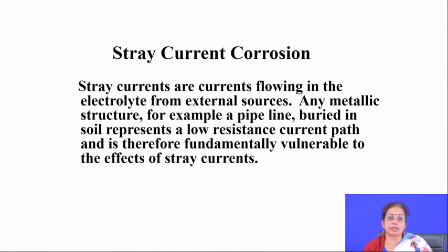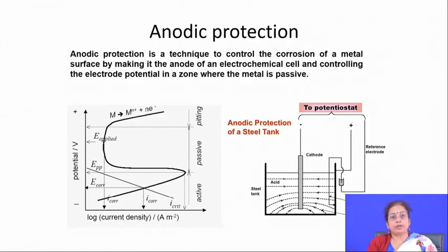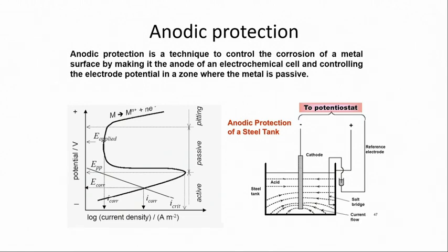Whenever you use cathodic protection, particularly below the earth, especially when you connect it with DC sources, you will find that if there is any other corroding species, it gets corroded away, so that gets further trouble. So, you have to be very careful in building a structure next to the cathodically protected structure, so that it cannot corrode.